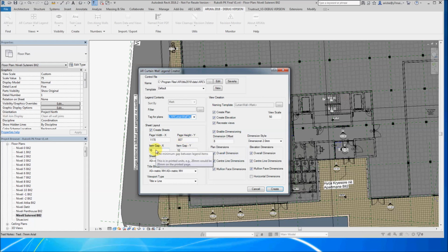So we're working in millimeters here today, and these millimeters, unlike our AR Legend, are in fact printed sheet millimeters. So 1170 is for an A0 sheet basically. A bit less than a full A0 sheet, but it's a measurement that you could take with a ruler on the final printed output. Likewise with the gaps, 10mm is a 10mm spacing on the final page.